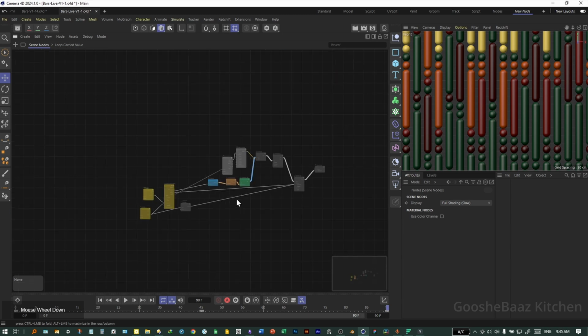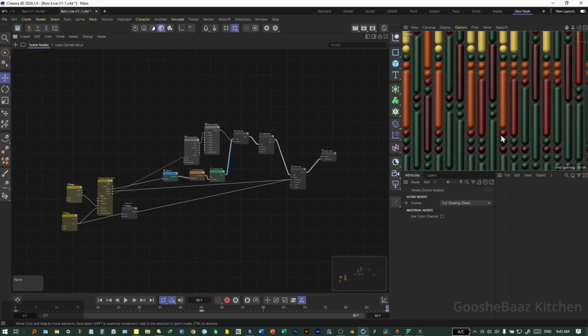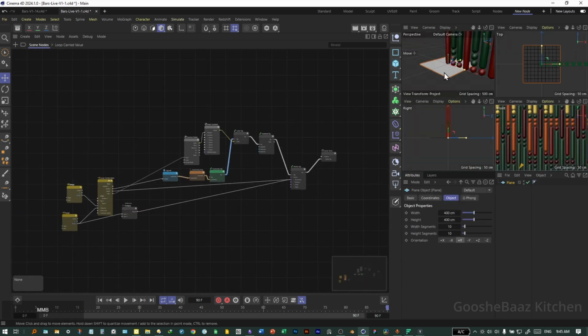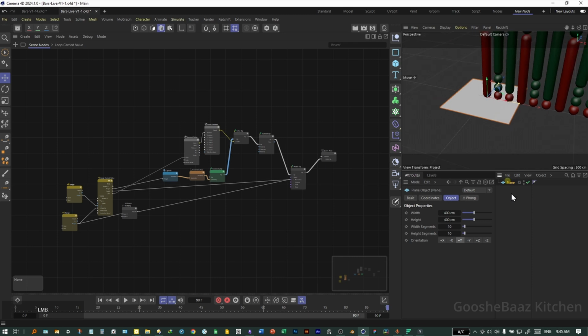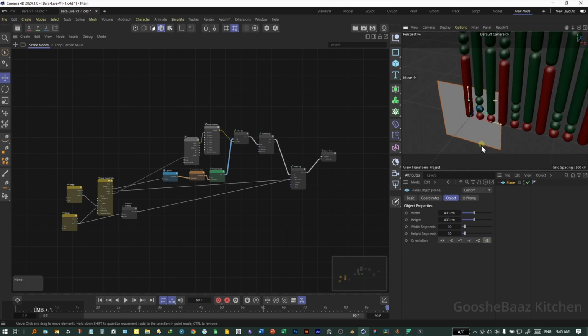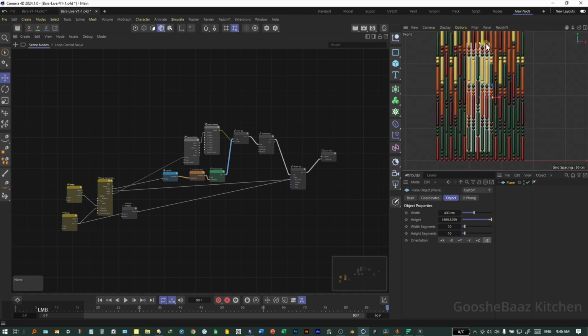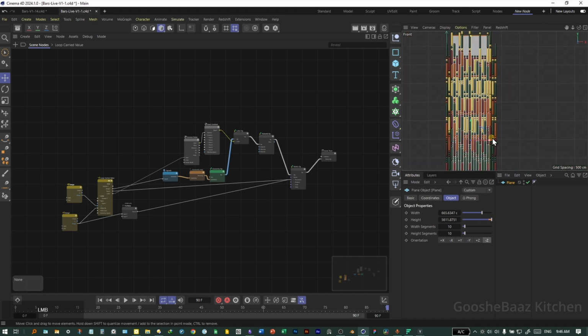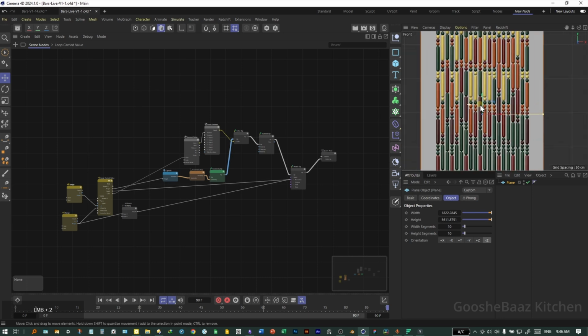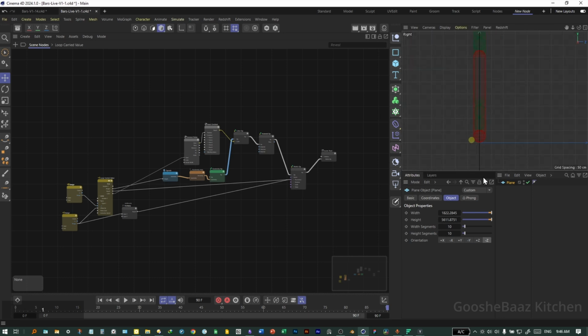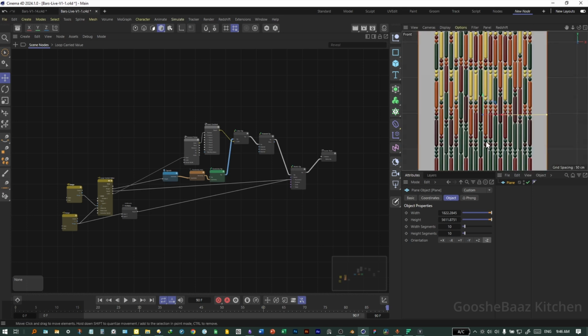Okay, let's add other elements to the scene. Add a plane to the scene. Come to viewport here. On the plane, select something like positive Z or minus Z is better here. Come to front view, put it wherever you want. Change the size of plane to cover the background. On the side, let's push it out a little bit to not intersect with the cylinder bars.